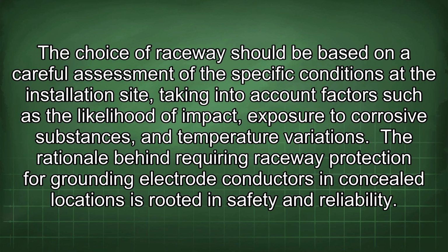The choice of raceway should be based on a careful assessment of the specific conditions at the installation site, taking into account factors such as the likelihood of impact, exposure to corrosive substances, and temperature variations. The rationale behind requiring raceway protection for grounding electrode conductors in concealed locations is rooted in safety and reliability.